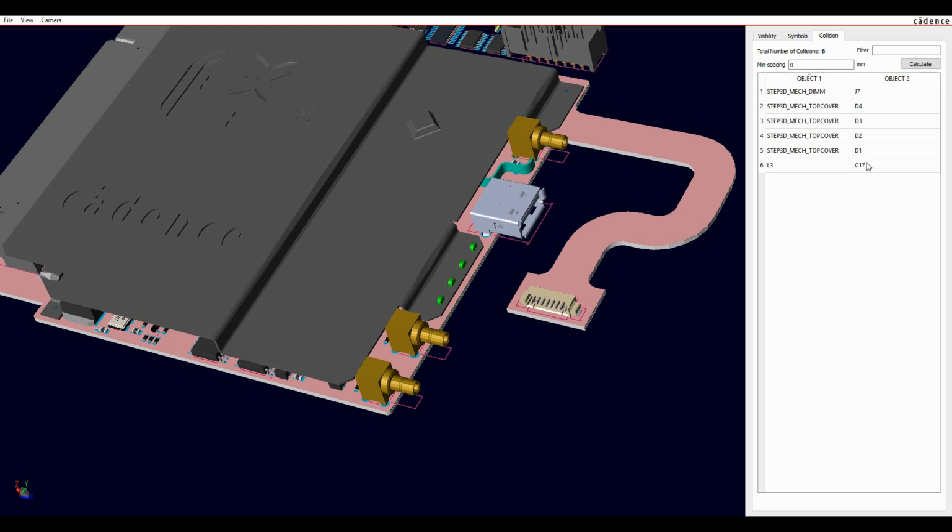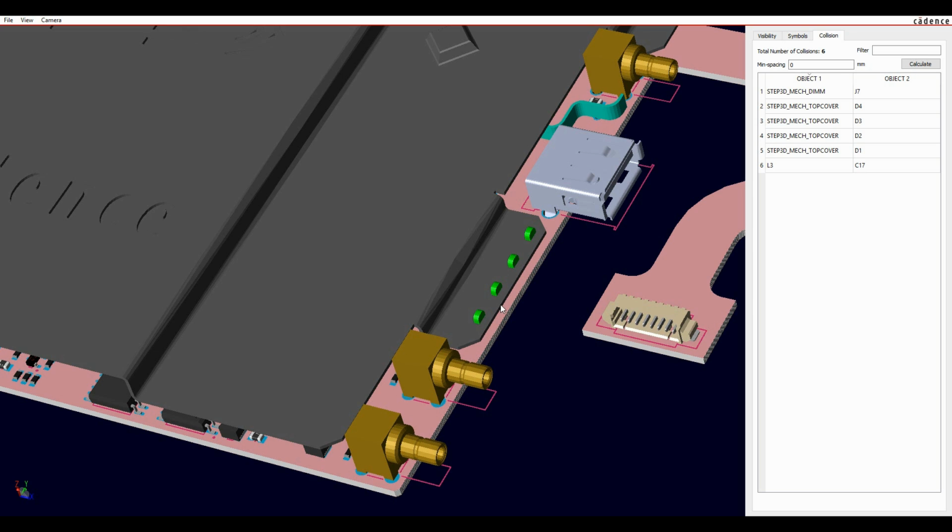In this kind of process, normally what people do is they would export an IDX or an IDF file or even a step file, go to the MCAD engineer. The MCAD engineer would then run a clash detect in the tools that he's using, SolidWorks, Pro Engineer, and then send the information back to the PCB designer. He would move the components, and then you would repeat the step to make sure you had no clashes. Being able to do this inside PCB editor tools can obviously save you quite a lot of time from that point of view. You can see the clashes straight away.